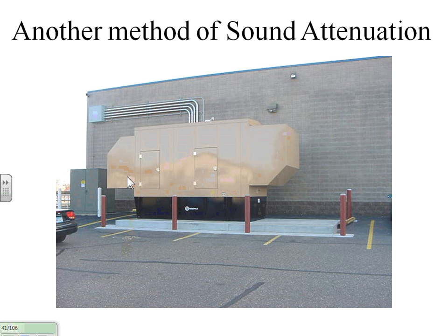Here we're turning the air as it's coming in. We've got negative pressure inside the enclosure, pulling air in through the inlet, which is here. We're turning it and bringing it in. Again, you can't get straight out through those inlets, so that's sound attenuating there, and we're sound attenuating by pushing it up on the outlet. And again, the dual containment tank sitting below it.